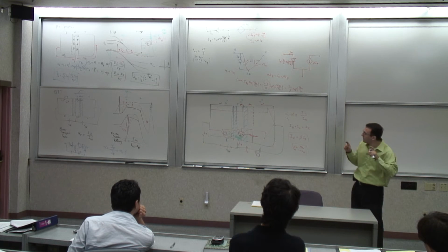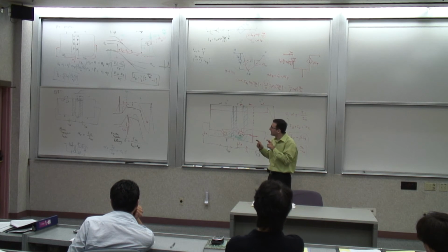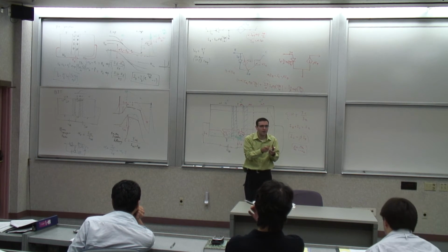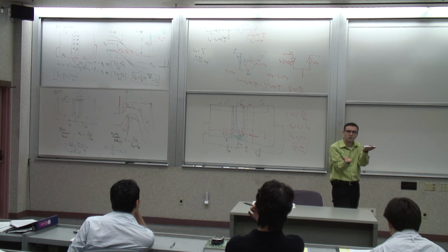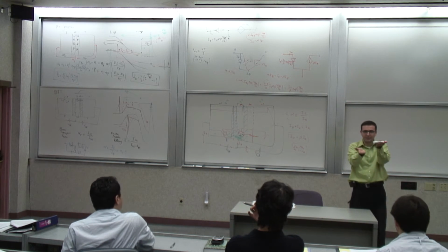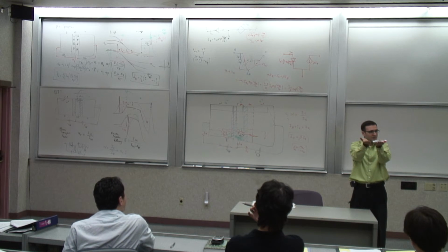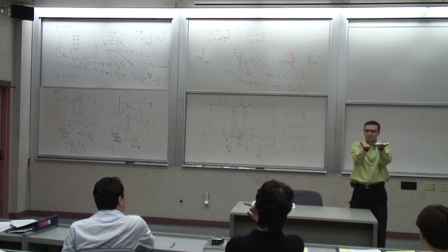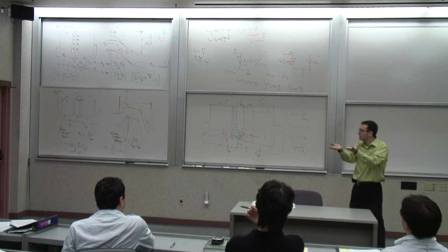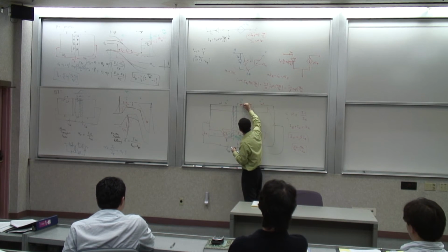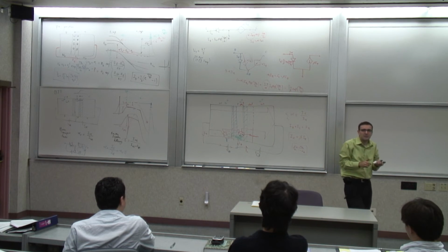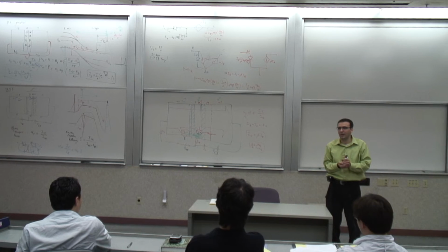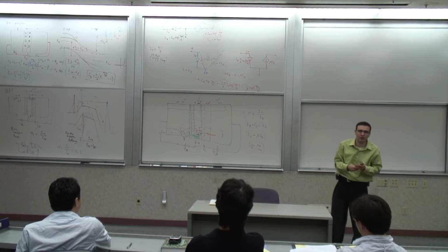But now, that means that for a given gamma, I can relax the ratio of the doping concentration on the emitter and the base side. So if I have that band gap engineering, I can increase the doping level on the base side, maintaining the same gamma. So I can make up for it. It allows me to increase NA because I have gained through the band gap engineering, and hence increase ND, and therefore reduce the resistance of the collector and the resistance of the base. And that's why HBTs are generally faster devices than standard homojunction structures.